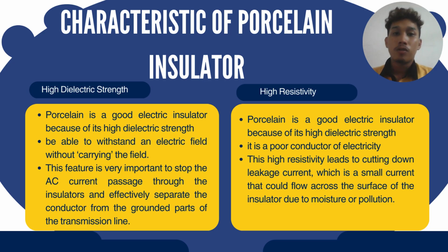We go to the characteristics of porcelain insulator. First, high dielectric strength. Porcelain is a good electric insulator because of its high dielectric strength, and it is able to withstand an electric field without conducting. This feature is very important to stop the current passing through the insulators and effectively separate the conductor from the grounded parts of the transmission line.